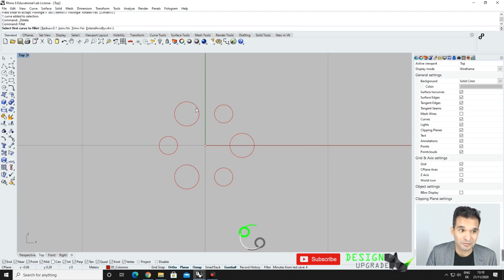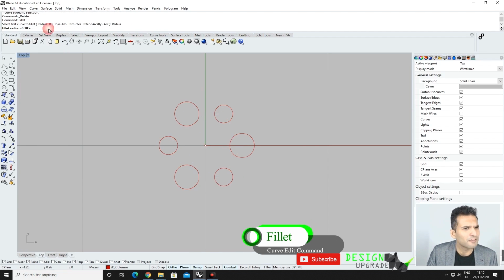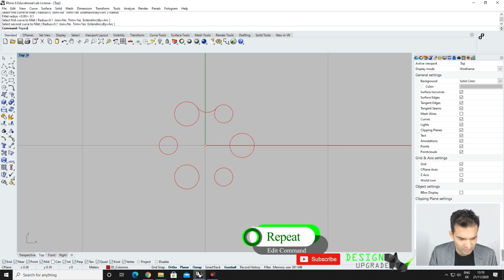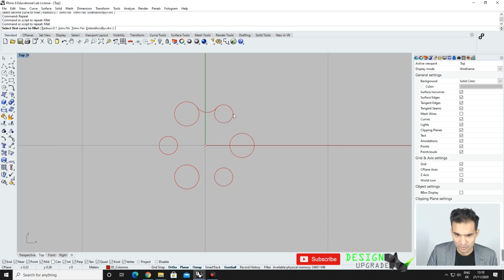Now, I do not want the hexagon shape, I want to create a fillet. And I'm doing it a bit faster to not bore you. Now the fillet radius, again, if it's 1 right now default, that won't work. We need to scale it down to the scale that we're using. 0.1 should be good. Let's try that. 0.1. This guy and this guy. Super. It works. So say repeat. Say fillet. And 0.1 and go all the way like so. Just the outer side. You could also array that.